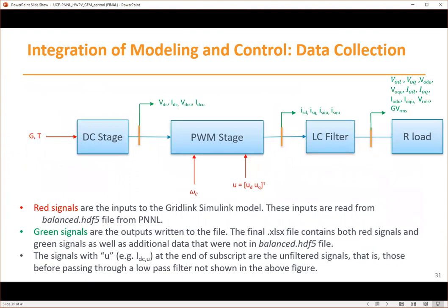So our control basically allows us to use the dynamic model of the system to ensure GFM and GFL performance. So it's critical for us to get a good model, and the Hammerstein-Wiener model is the one that we're moving toward. What's shown here on the screen is the data that we collected using both the Simulink model of the grid-following inverter, as well as, in the near future, the physical grid-following inverter itself, in terms of the HW modeling.